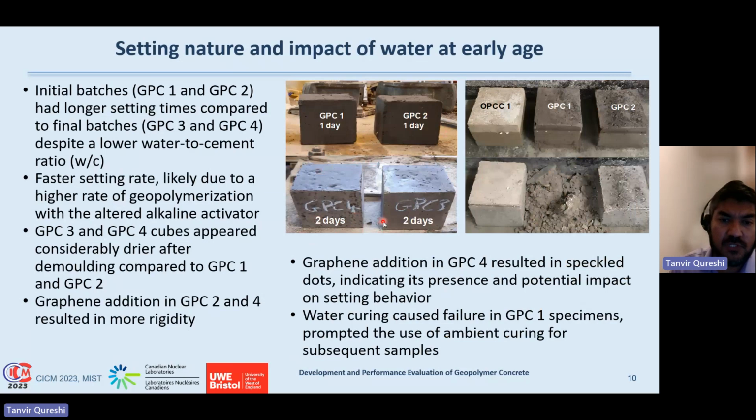And we have also looked into the geopolymers. If we immerse them under water after just the initial day of casting, like after we cast the samples and after 24 hours, if we started to cure them in water like typical Portland cement concrete, we see that the systems fail, because geopolymer needs curing in dry conditions. Unlike typical Portland cement concrete, water is not required anymore during the curing process.